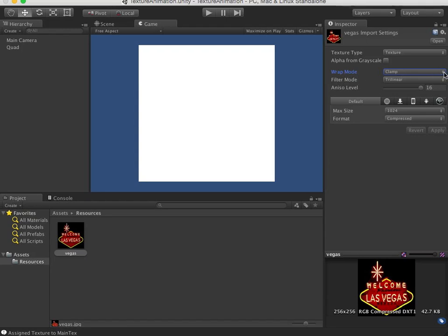So either you stop at the final value, so you just get the border appearing and repeated, which is clamped, or you repeat. It just starts from the start of the texture again and repeats it. That's a very common one, repeat, because that's often used when you want to simply replicate the texture across a surface, such as a rock face or wood or some sort of paint texture, whatever. So repeat is often a common one to use.